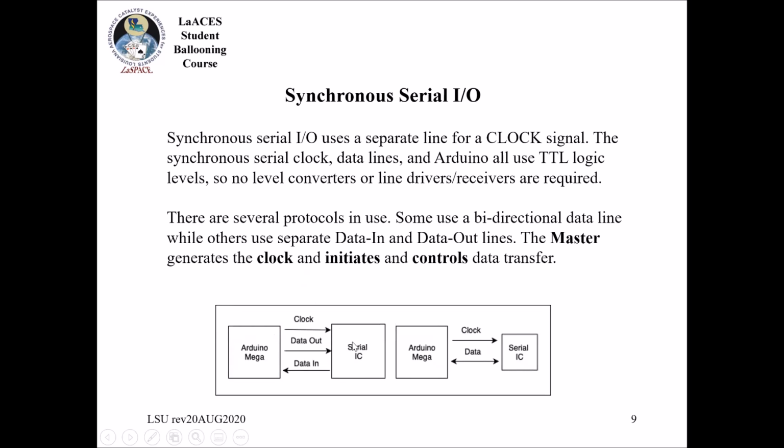So that means that whenever I hook up the lines, this one is typically a transmit. This needs to be connected to the receive line of this one. And then this data in needs to be connected to the transmitter side, and then it'll be in the receive side here. So we call that crossover. You'll have to cross the cable over.